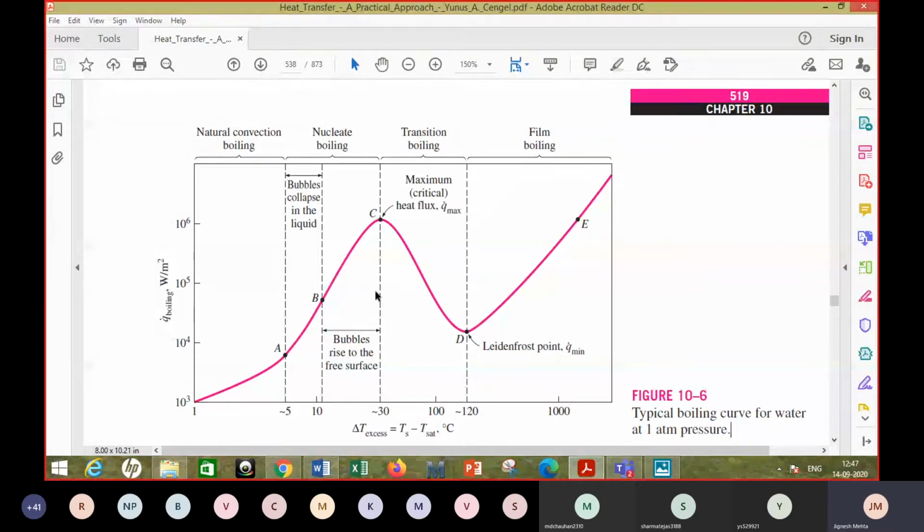That's a very high heat flux, and obviously the heat transfer coefficient is also very high, which can provide such high heat fluxes, right? Because basically Q dot is equal to H delta T. So if at a particular delta T, Q dot is very high, rising exponentially, then the corresponding H value is also very high.